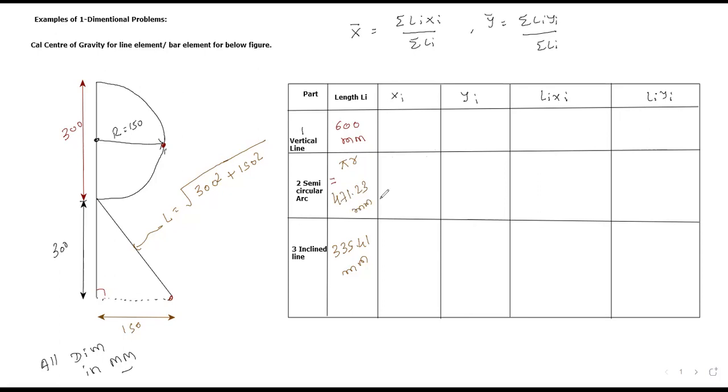Now before calculating the center of gravity, you need to decide the reference axis. For that, you have to see your geometry from the extreme left. Whatever the first point of the geometry, at that location you have to plot a reference y-axis. I am changing the color also. So can I say that this entire line is your reference y-axis? Yes or no? Because your geometry starts from there. Please confirm me.